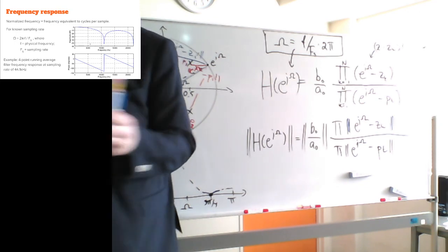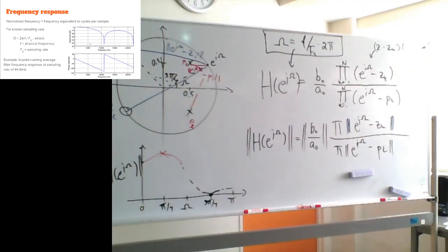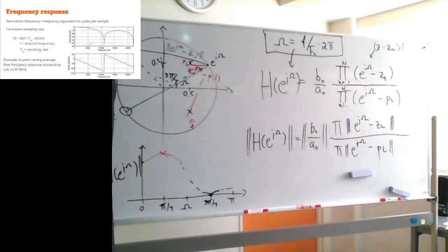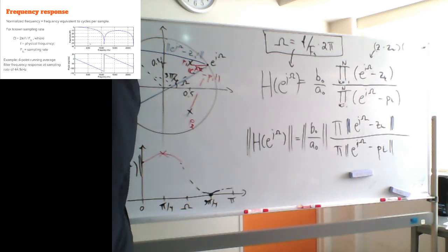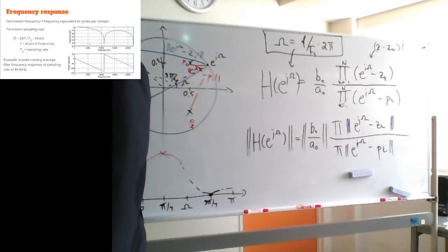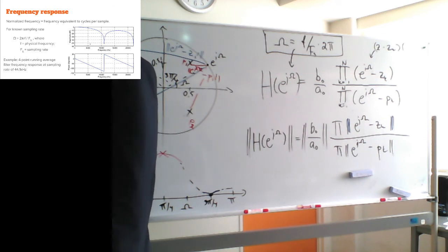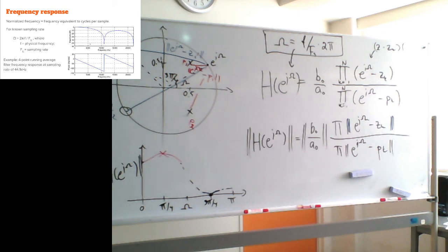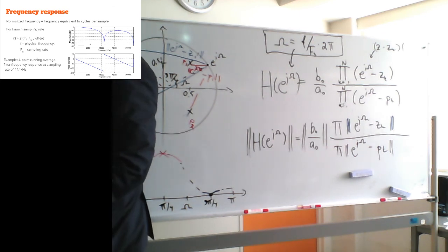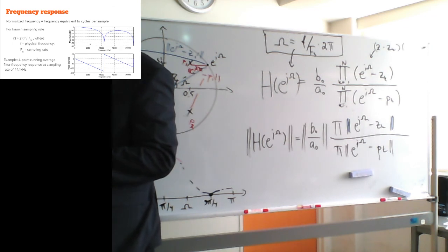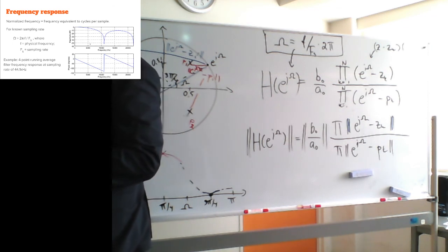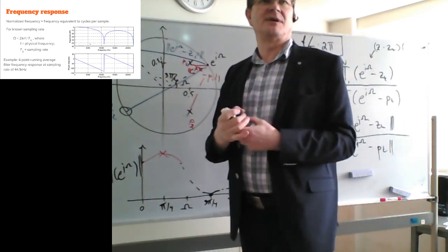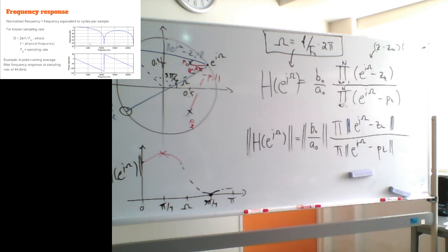But, well, okay. Now speaking about the running average filter, if you think of this as a low-pass filter, this is not a really good low-pass filter. This is then the stop band, and you have stop band attenuation of only minus 10 dB. That's not good. But it reduces a little bit of noise, but not too much. We can do better.